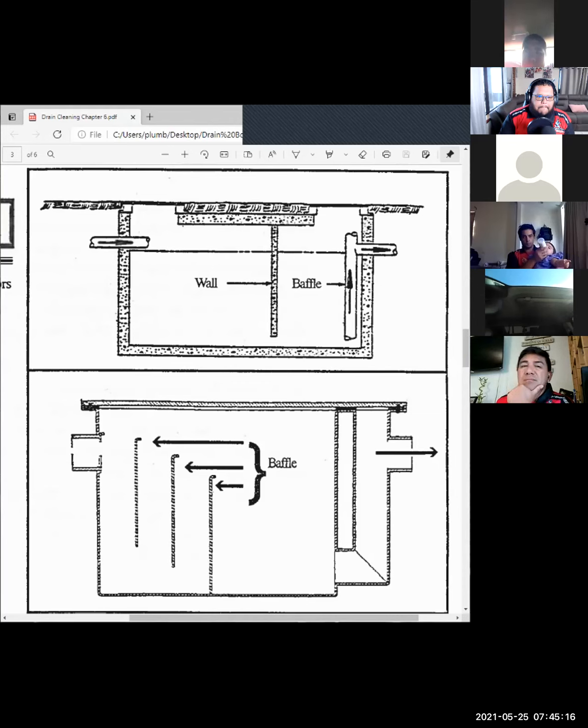Because, one, as Josh said, you can see the exit pipe. Now, if the exit pipe is partially blocked by grease and things, which is not a pleasant job and something we're not doing a lot of, but if you break around the outlet of that grease trap and find it was just a bunch of grease clogging up there and building a little dam, then you might be all good to go again.